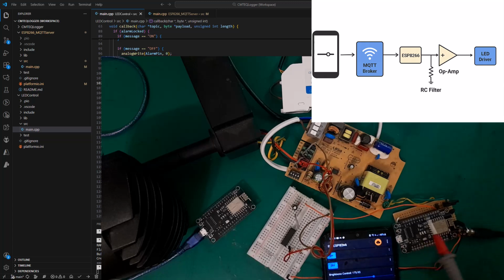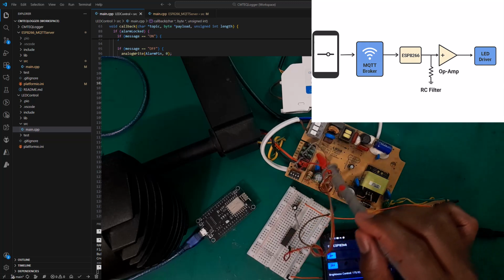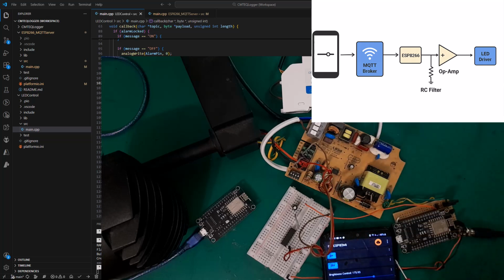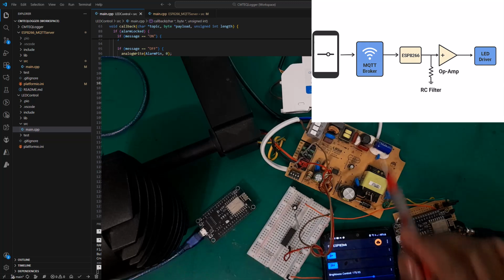Then at any given time, let's say our duty cycle is 50%, we're going to have about 2 volts or 1.5 volts depending, and that is then going to be scaled up and fed here into the dim plus and dim negative. So that's basically how this circuit is going to operate. And from there, the LED driver is going to do its magic to control the dimming.